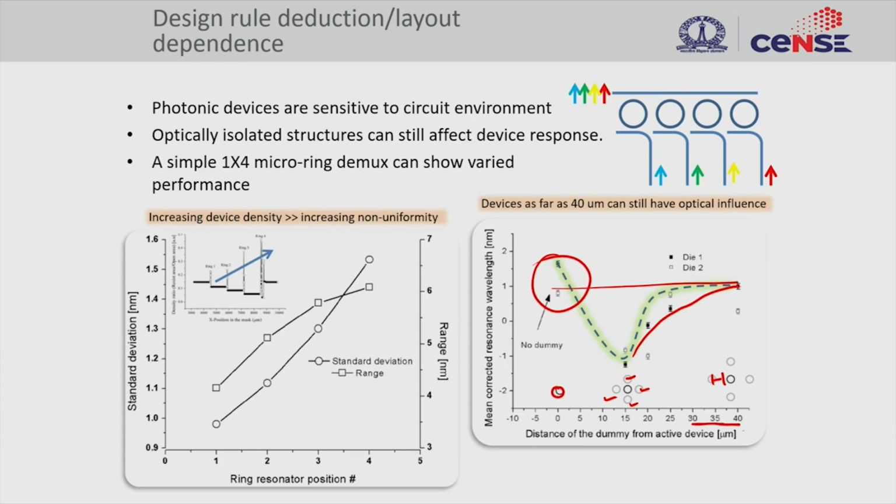So this influence is coming from the wafer scale plasma processes that we are doing. If you remember the plasma process, when the radicals come onto the wafer surface, the radicals can migrate based on the energy and substrate temperature and everything. So based on this, it can diffuse on the surface, and this diffusion length can affect your neighboring device uniformity as well.